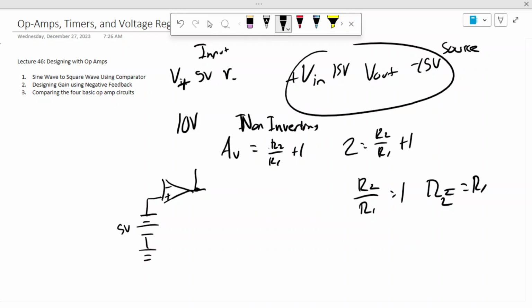And then we have our two resistors. And then this goes to ground. And this point goes back to the inverting input. So as long as they're the same, we will get 10 volts out. So I can make this 2K, I can make it 5K. It really will give me the same amplification either way, as long as they're the same.